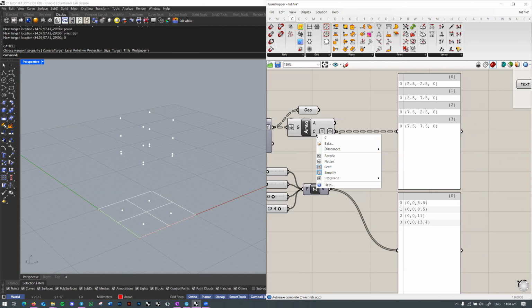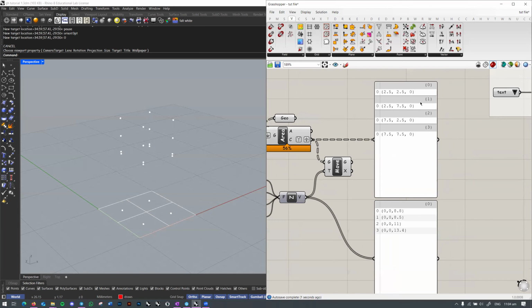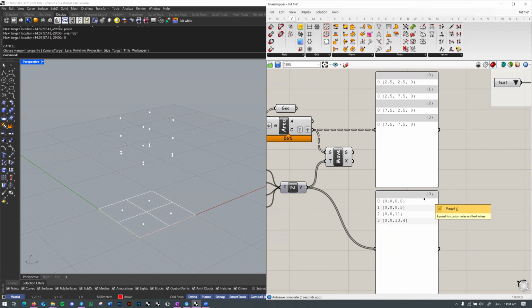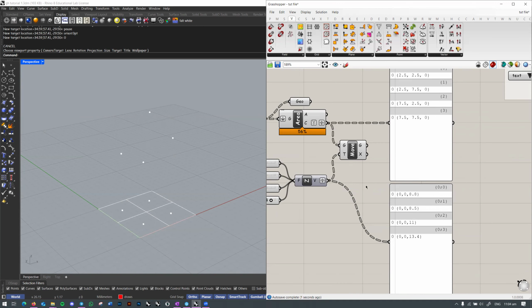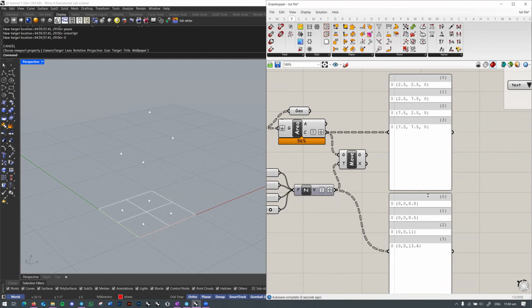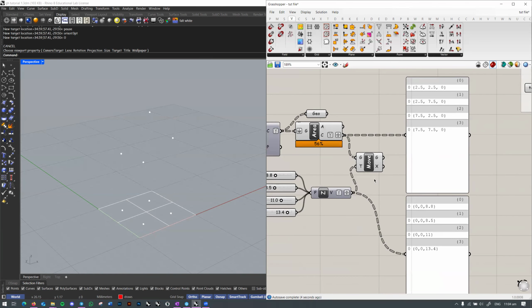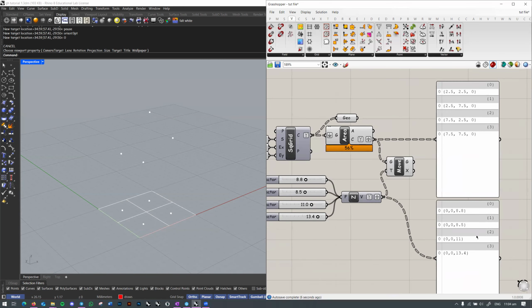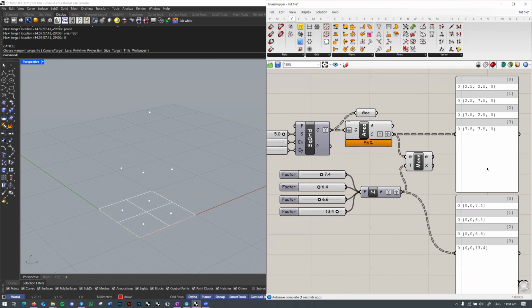let me change your plans. Let me flatten that and then simplify this. Yeah. So now we have list number 0, 1, 2, and 3. But here is only list 0. So what we can do is we can graft our instruction list as well. And because our instruction list and our data set list are the same again, even though that is now a grafted data structure, we can control them individually as well, right?